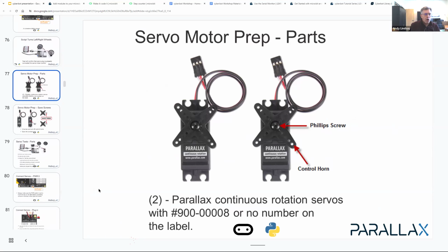Do we need power off again? Yes, absolutely. Turn power off. You don't really need to disconnect the micro:bit from the laptop if you have the PWR switch set to 0. It's an okay extra step, but I don't think there's really a chance of hurting anything by not unplugging the micro:bit.